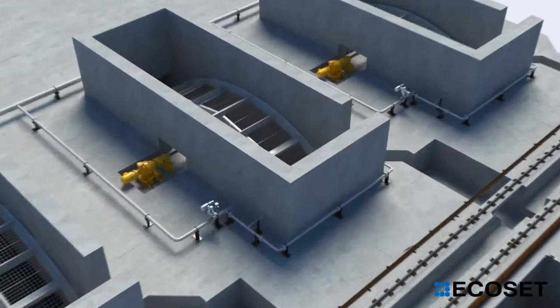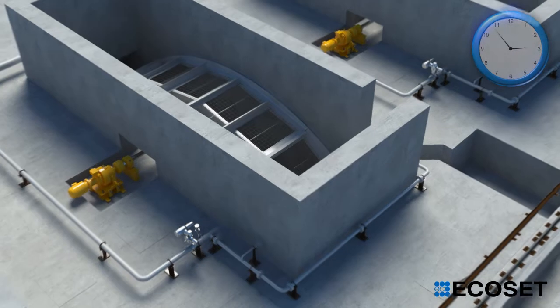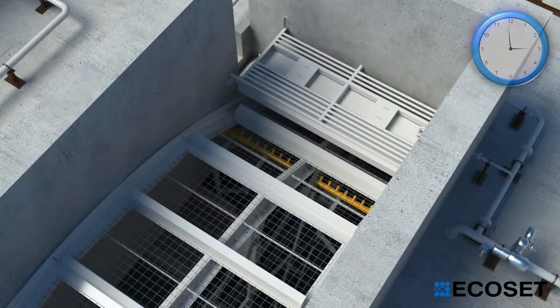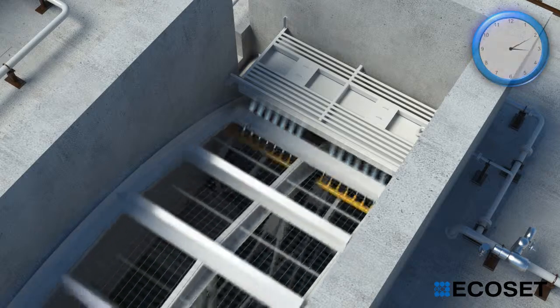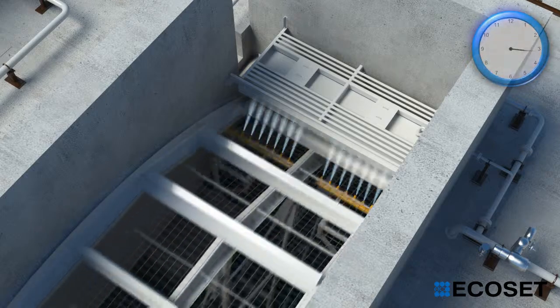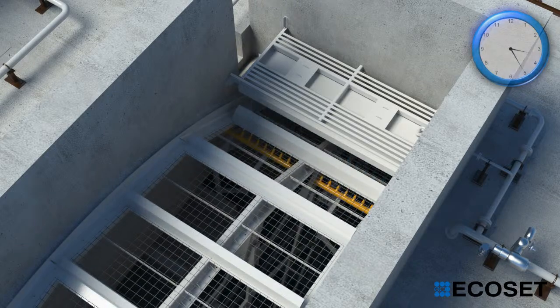Under the operating method of periodic time control, drum screen is operated once every 7 hours and 40 minutes for 20 minutes, 3 times a day by the time sequence. The interval and running time can be adjusted in the settings menu. The initial startup method of drum screen for periodic time control is the same as that for differential level control.